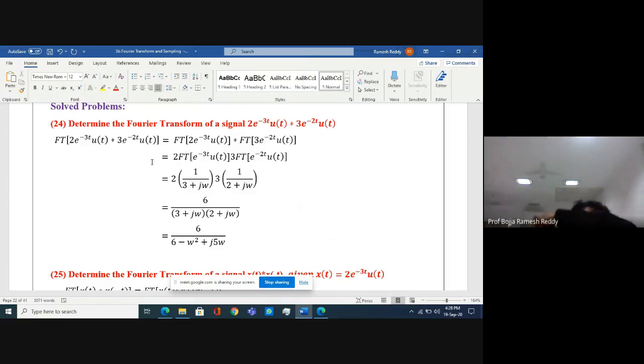They are asking what is the frequency domain of the convoluted signal. What is the convolution theorem? Convolution in time domain leads to ordinary multiplication in frequency domain. So we apply the Fourier transform to the first signal and to the second signal, and between those two, a normal product.